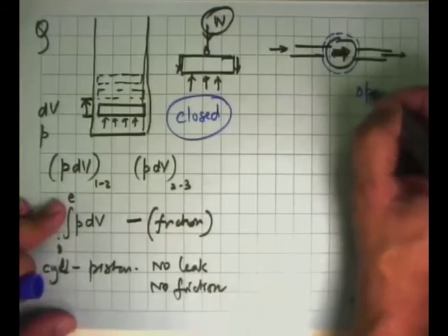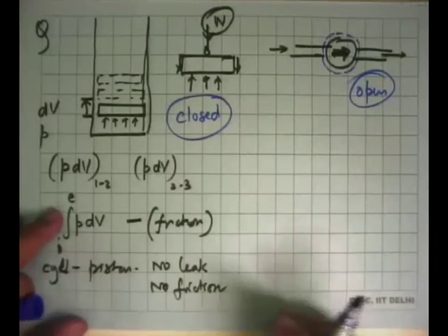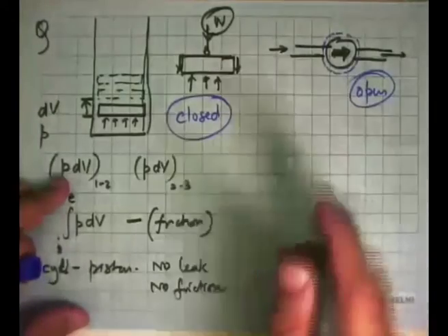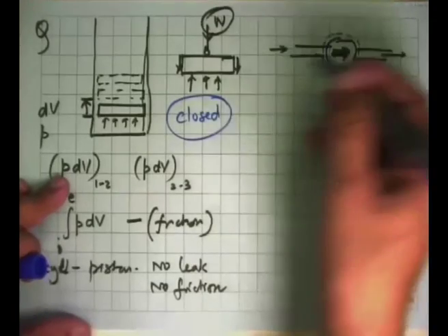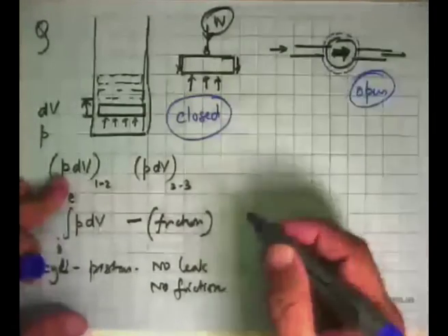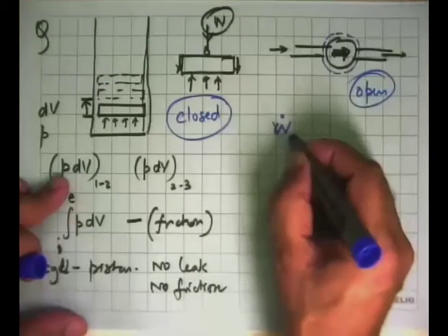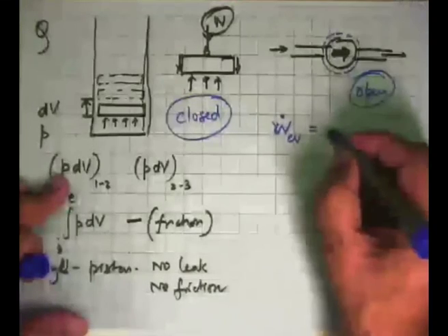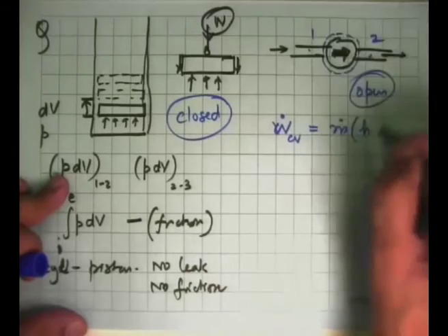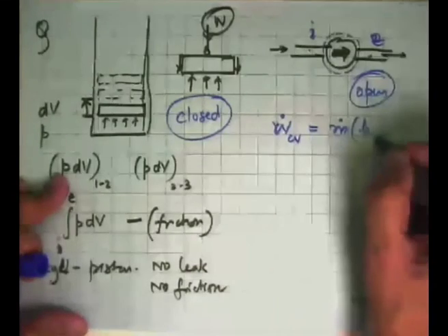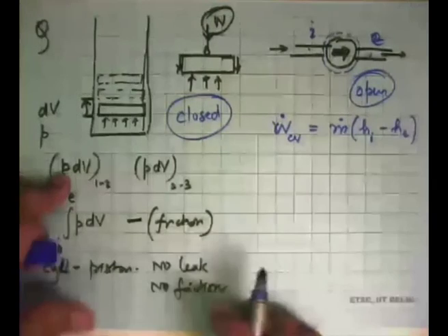This is an open system into which flow is coming in and going out. So the equation that comes out for this particular case is the full first law equation, and if we simplify by neglecting potential energy changes, kinetic energy changes and assuming steady state, then you will get W dot, and there's no heat transfer also, W dot CV is m dot, say this is state 2, this is state 1, or this is the exit, inlet, say hi minus he.